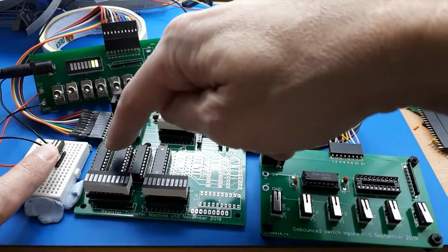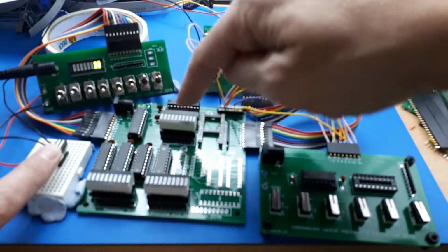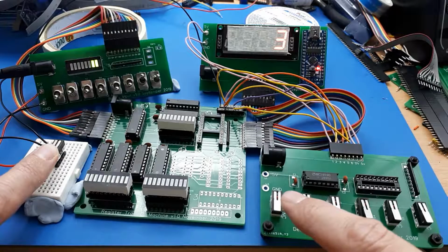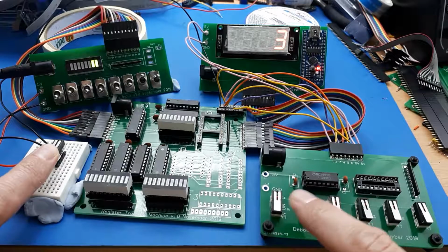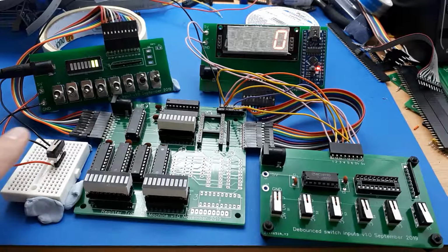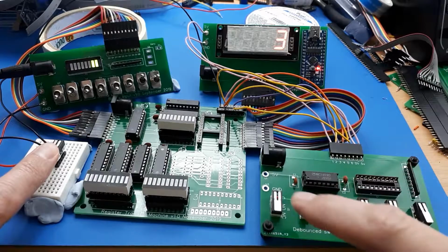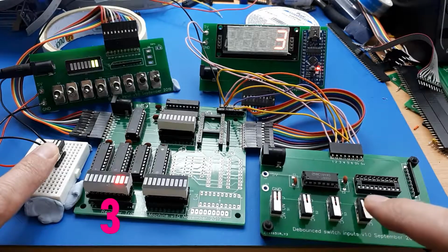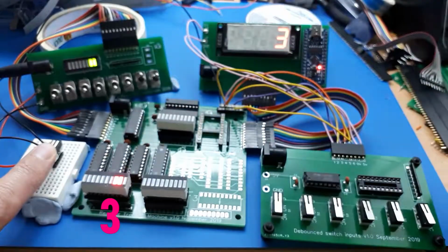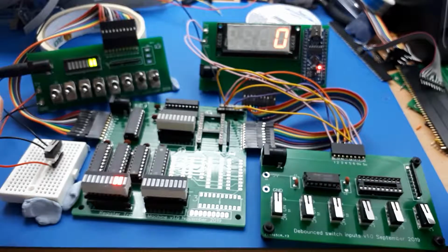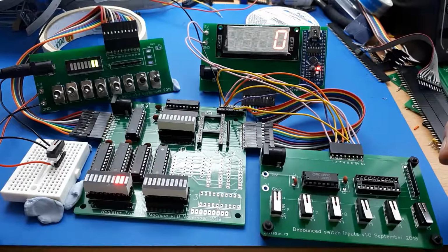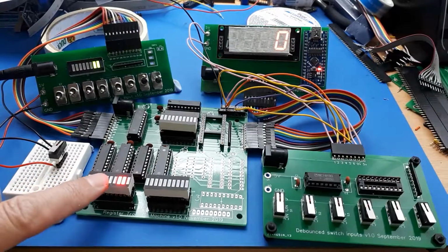Now I've implemented register 1, register 2 and register 4, and I've connected those up to these switches here. So we have publish for register 1, 2 and 4, and we have store for register 1, 2 and 4. So if I publish a 3 onto the data bus and store that in register 1, then the value of 3 is now stored in register 1. And if I stop publishing onto the bus, there's currently nothing on the bus. It's actually zeroed out because of the grounding resistors here. So we've got the value of 3 stored in register 1.